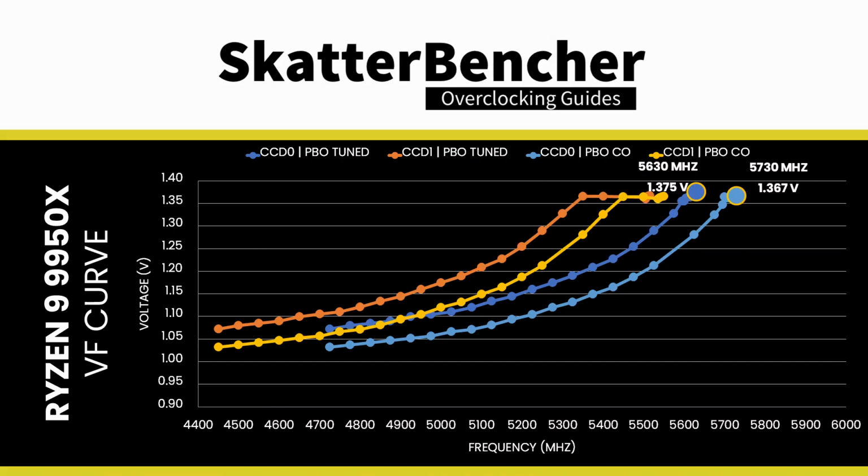The highest frequency with all 16 cores active has increased by 100 MHz, from 5630 MHz to 5730 MHz on CCD0. These higher frequencies are now possible because our Curve Optimizer undervolting pulled them below the 1.375 volt threshold. Curve Optimizer is a very powerful tuning tool. It's simple, but not simplistic. And the more you dig into how it works, the more intricate it becomes to apply to your system and to squeeze more performance out of your system.